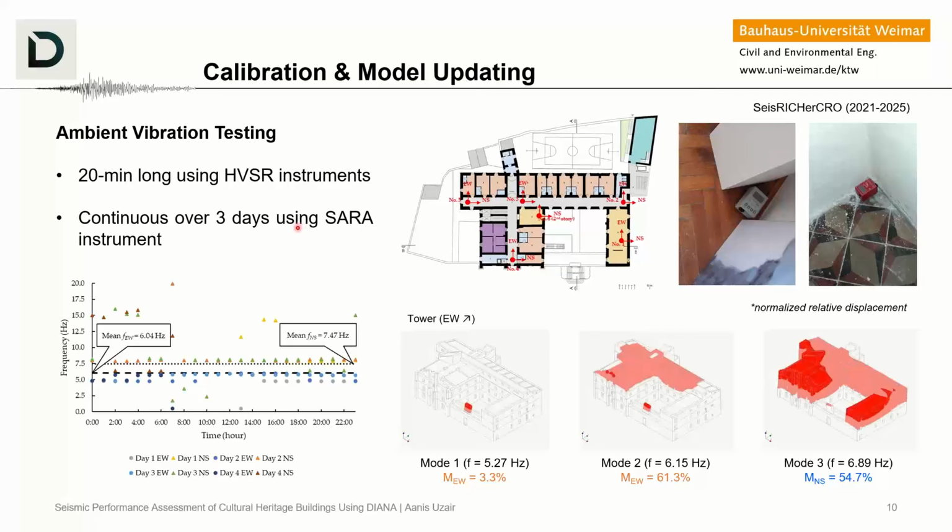And once we see that the error is reduced, then we come back and we look at the mode shapes, and we see that the modal response for these frequencies looks like that. What you see here in the first mode is a frequency that we do not see in the experimental campaign, because it is a local frequency of just this clock tower from the external facade, or from the front facade of the building. But what you see in modes 2 and 3 are the frequencies which correlate to the frequencies that you see from the experiment, or from the actual site.